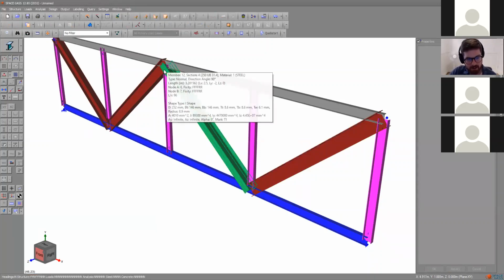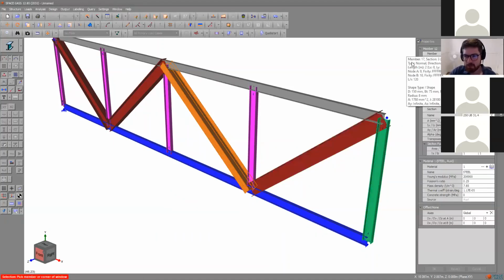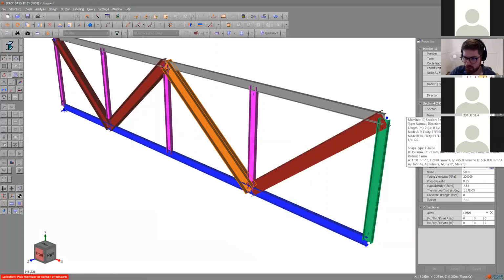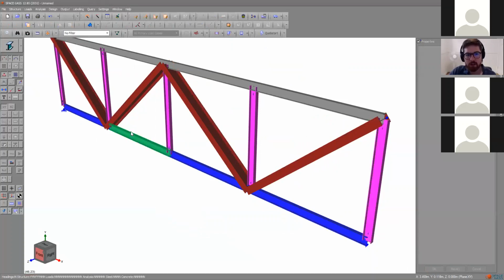The difference is, you saw there, that's changed it for a single member, member 12. Yeah, so if you just selected the other members, it'd be doing the same thing? It'd be doing the same thing. Whereas if you change it in the section tool, section 4, that changes all the sections that it's attached to. So that's a really good question.